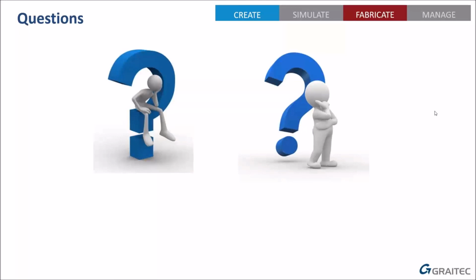So you might want to just choose the option. They'll be on the side, so it'll be on the left or the right for the post position. And you would probably just set the option to be direct welded for the post connection, and that will give you the chance to extend the post down the right height, but not put any plates on. Then you'd have to change those welds to site, because obviously it's not literally welded straight to the channel. And you could add a custom connection to put the toe plate in and the palm plate on the side of the rail. You'd have to adjust the offset of the railing to allow for the thickness of the palm plate you want to put on.